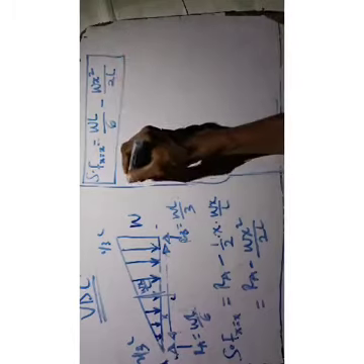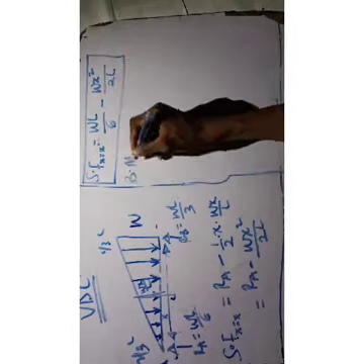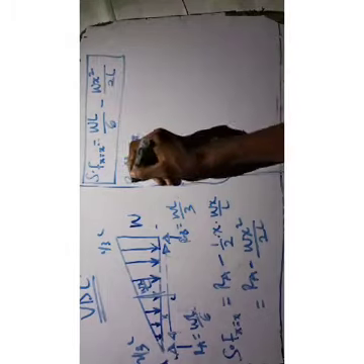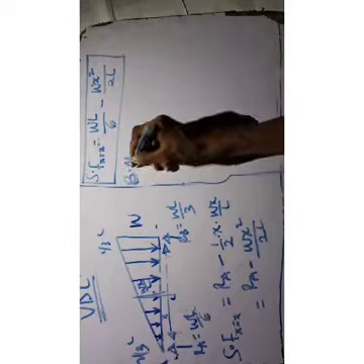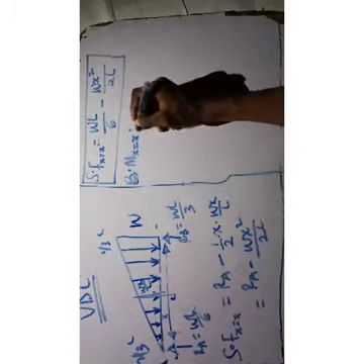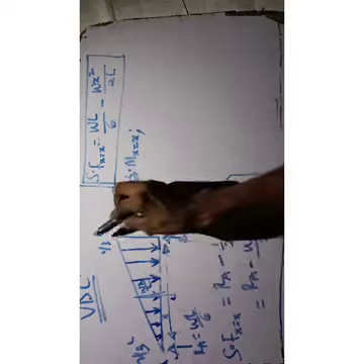So now for the bending moment at any cross section, it won't be logical to solve each step by step and apply the same rule. It's much better you just apply the formula and be fast about it. So the bending moment at each section can also be found by taking moments about a point, let's say point B. At any section, just take your moments around it, and it covers 1/3.